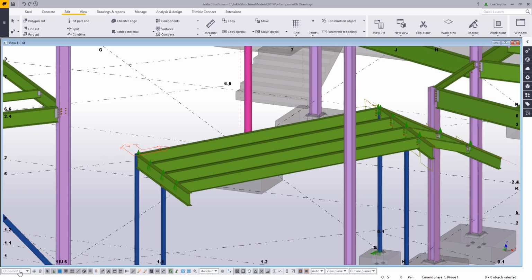And then you'll notice down here this new work plane handling tool that will allow me to save these user coordinate systems. So if I wanted to save this, let's say that we call this my roof slope. I'll just type that in, click on add. And then that's going to store that user coordinate system so that I can easily refer back to that. What this work plane handler tool also does is it stores my model origin, any base points that I've created, and any other coordinate systems that I have modeled.